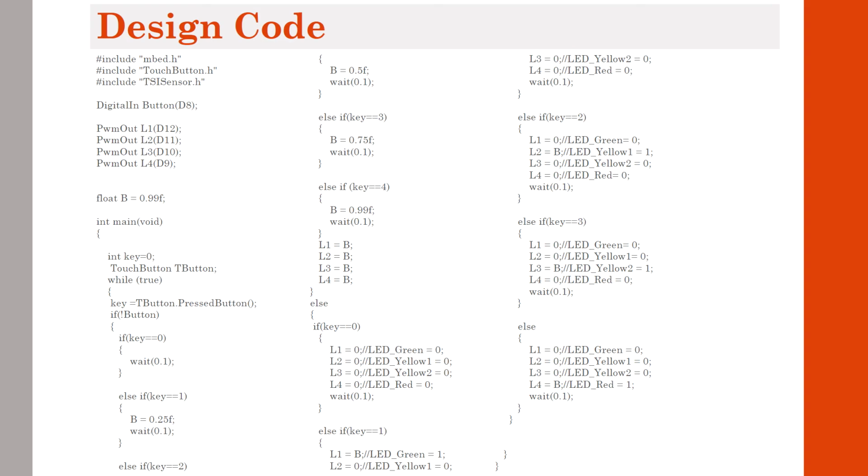Following that, a collection of else-if statements are responsible for the default function of the slider, and that's again to turn on different LEDs when different positions of the slider are touched. Since we wanted only 1 LED to correspond to each discrete range of the slider, all the other LEDs are configured to be off while 1 of them is on.